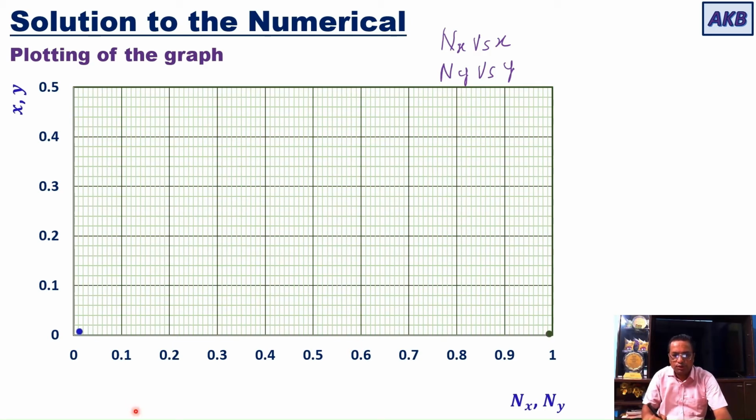So I'm showing simultaneous points for the two layers. So this is water layer, this is isopropyl ether layer. And since these are equilibrium concentrations, they will be connected by a tie line. The next pair of points is, this is the point in water layer, this is the point in the isopropyl ether layer, and now they are connected with a tie line.